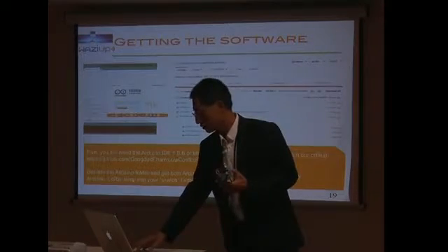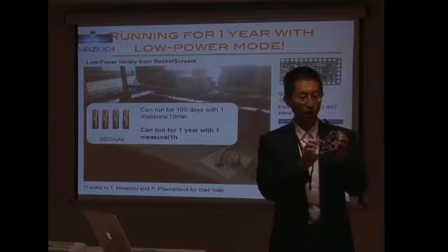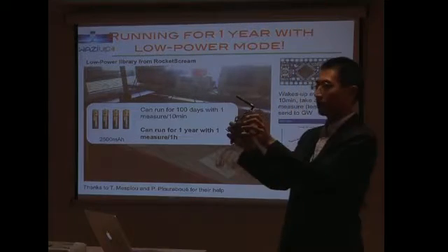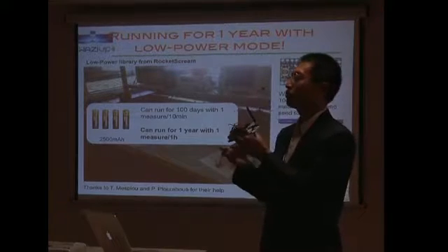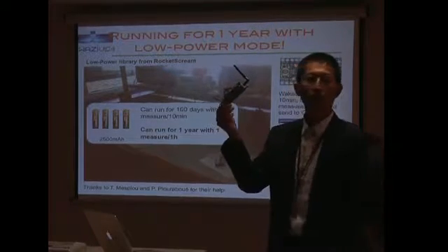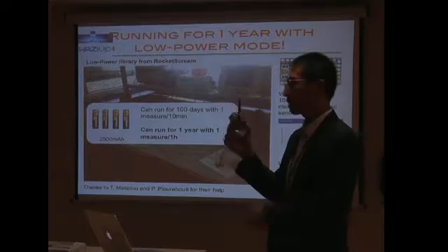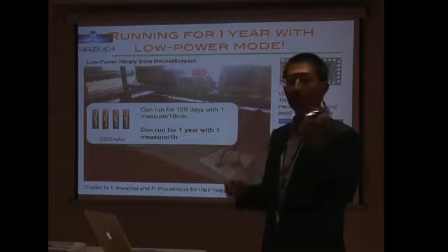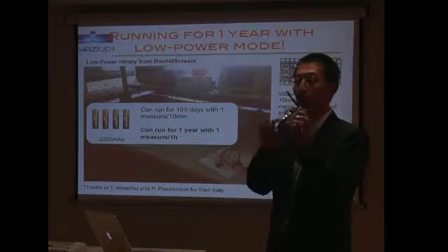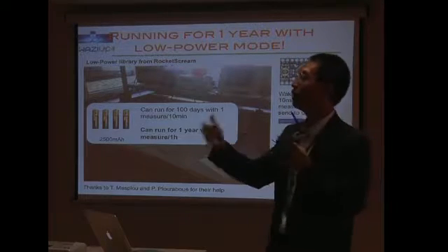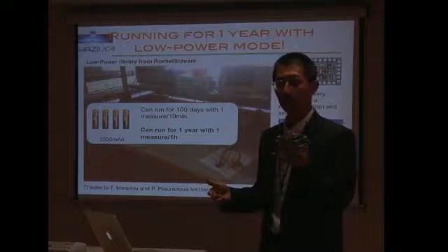And the nice thing is we integrate low power management. So we have 4 AA batteries here. This one has been programmed to send 1 measure every hour. And we are capable of running for more than a year with 4 AA batteries, with low power, duty cycling, and so on.